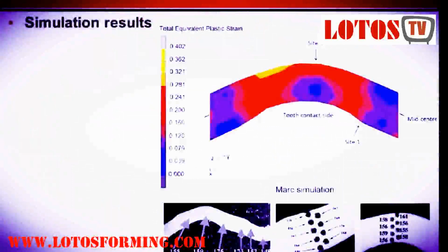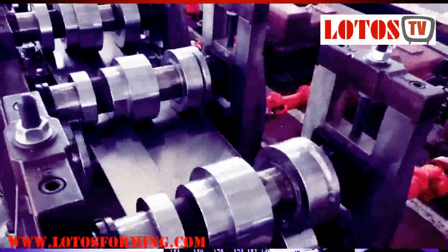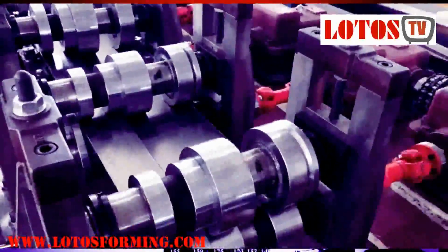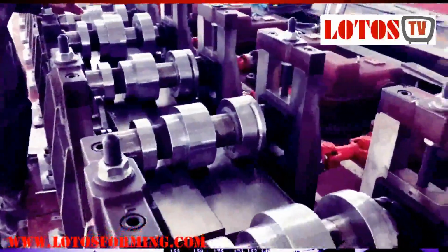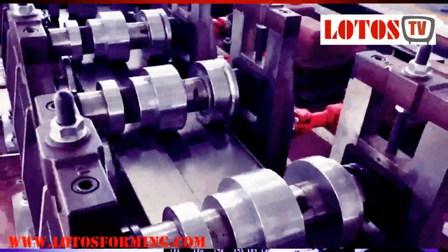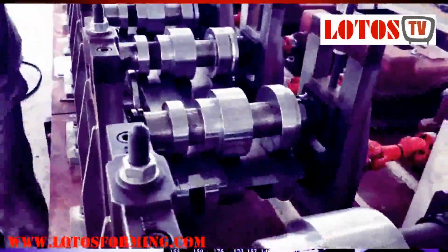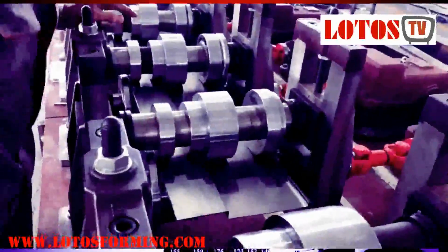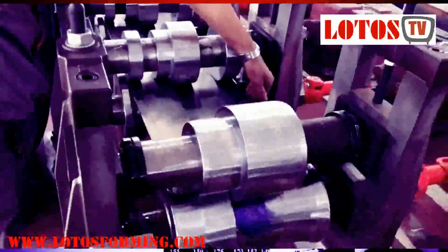The next validation is we look at the plastic strain pattern developed in the dimple, looking through the cross section, and compare with the micro hardness test data. As you can see at the bottom of the slide, there's a relationship between the micro hardness data and the plastic strain development.